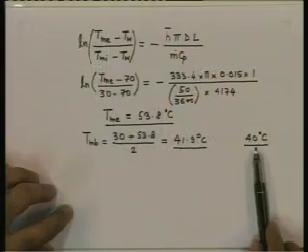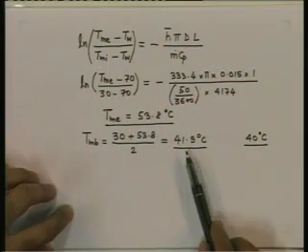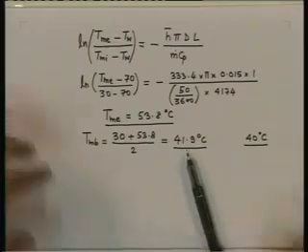If this assumption were to differ from this calculated value by a very significant amount, say 10 degree, 15 degree, then it is definitely worth redoing the calculation with the new corrected value of the bulk mean temperature, because the properties would change reasonably significantly. With a temperature difference of about 2 degrees C, they are unlikely to change, but anyway it may be a good exercise for you to check that out.